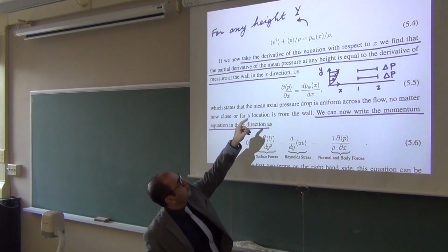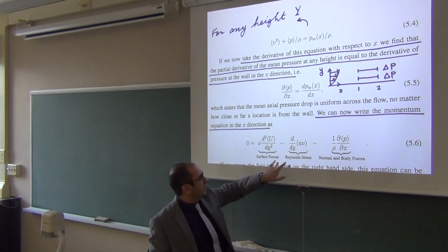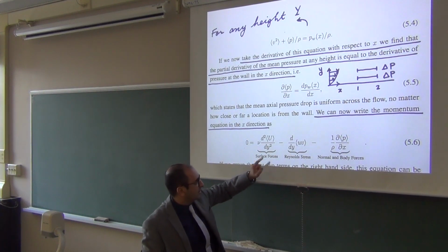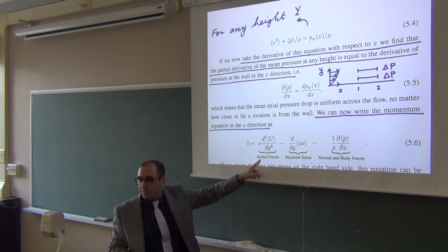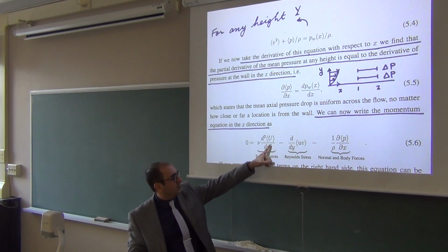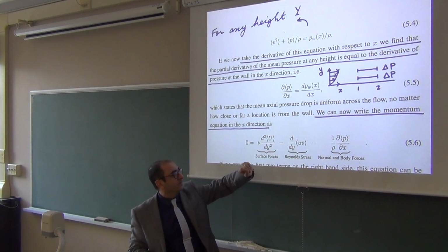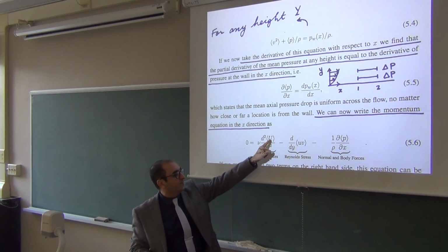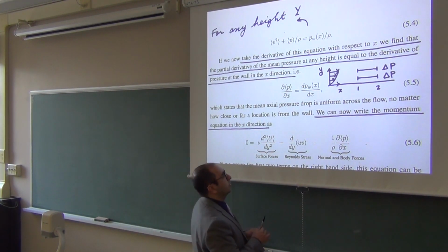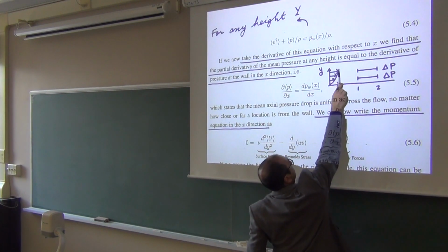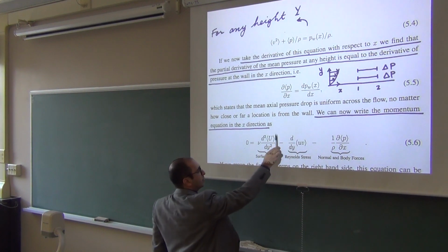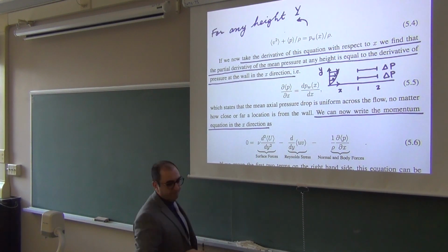It's not v squared anymore. But there is one extra term that's left from the surface forces. In fact, this term is coming from the Laplacian. Kinematic viscosity comes from there because u shows variation with respect to height. I'm just showing you, u is changing with height, right? So there is a gradient of u with respect to height. So the term for surface forces will be there.